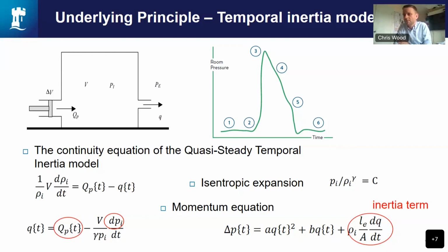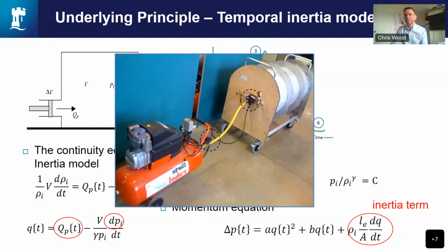Those first two components are related to steady flow, but the challenge has always been this third component, which involves the inertial term. Essentially, when you think about the change in velocity of the air going through those gaps and cracks, the inertia is actually a problem, because that represents unsteady flow. The challenge, therefore, is to create a pulse, and at least a part of that pulse where that unsteady flow part tends towards zero. It may never reach zero, but it's certainly a minimum, and there we can calculate